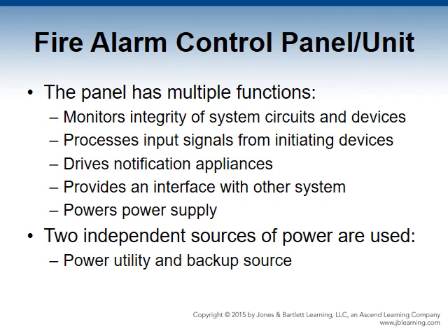The backup power source is rechargeable. Storage batteries or an engine-driven generator should be present. Storage batteries must be able to sustain power for 24 hours in normal ready mode and 5 minutes in full alarm mode at the end of the 24-hour period. These requirements are different for voice alarm communication systems and mass notification systems. If a generator is used, it must have 4 hours of battery capacity.